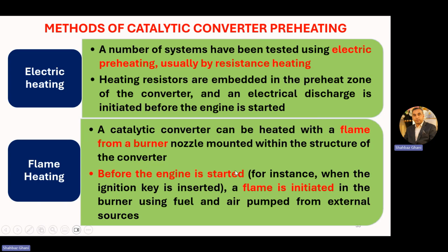Before the engine is started, for instance when the ignition key is inserted, a flame is initiated in the burner using fuel and air pumped from an external source. So we get some minor combustion there, which produces heat energy and heats up the catalytic converter.